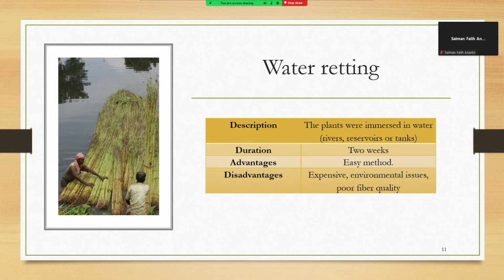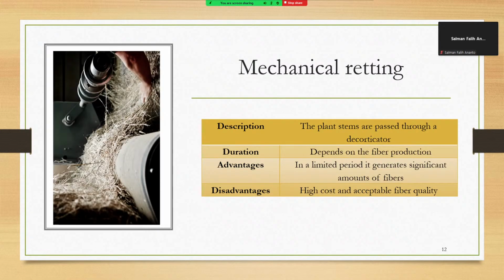In this process, the outer layer of the fibers, such as gums and stem skin, are eliminated by continuous feeding of the fibers into a machine. Later, the extracted fibers from the machine are repeatedly washed with water and dried for 48 hours in sunlight, eliminating the water content from the fibers. The mechanical extraction or mechanical retting process produces high quality fibers with shorter retting time. However, in respect of dew and water retting processes, that is the previous processes, this technique is more expensive.